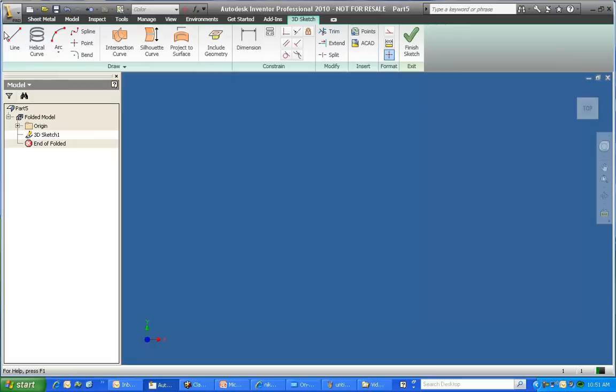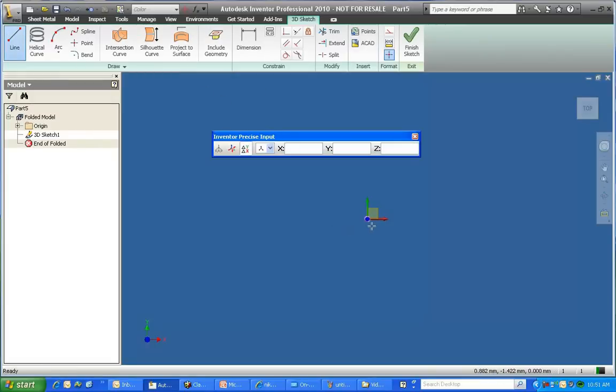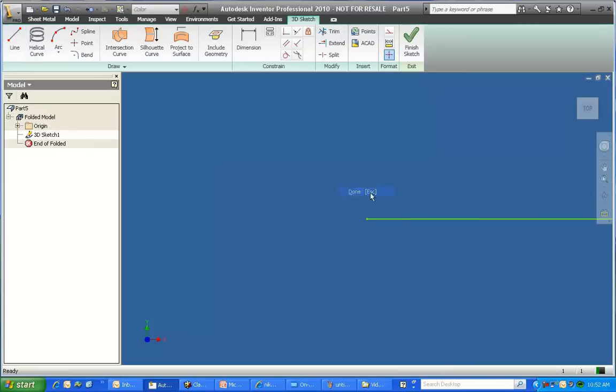Because I have nothing in here, I need to create something to attach my geometry to, so I'm just creating here a line that will serve as my perpendicular line to the plane of my spiral. So I start from the origin point and I go 100mm in one direction. So nothing fancy here, it's just the normal to my plane that I will be constructing on.